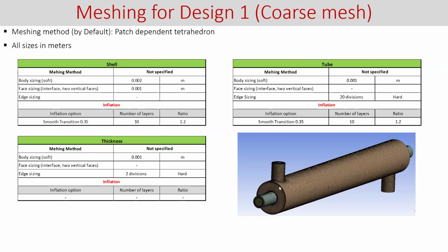Yes, definitely they are applicable. Yes, the time step calculation is exactly the same, although the numbers will be different. But it can be different for different cases, not in the process, but in the concept. For example, for an aerofoil, if you want to analyze the transient flow at high angle of attack, or the flow around a circular cylinder like vortex shedding. In this case, if there is vortex shedding around the circular cylinder like this one, then I would be going for the dominant frequency.